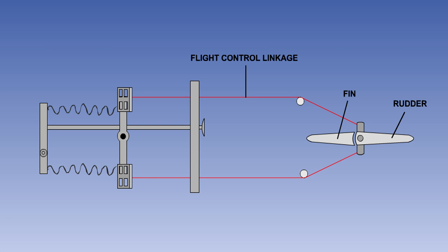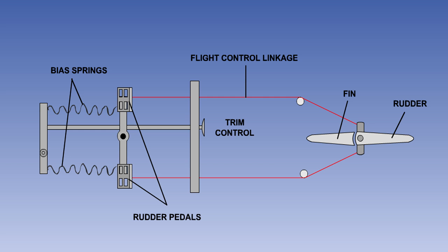In the spring bias type of trim system, an adjustable spring is used to reduce the stick force. No tabs are required, so the spring system does not have the disadvantages associated with tabs. The spring bias system differs from the other systems discussed so far in that the device is connected not to the flying control surface, but to the pilot's control. The trim control biases springs which apply a force to the control linkage to oppose the stick force.